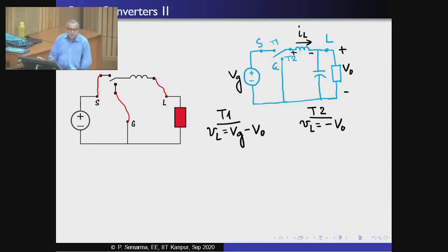Now, this is one interesting part. This is where we assign the signs of each one of these quantities. It is essential that you look at the circuit carefully before you put these plus or minus signs, because this is one place where students make a lot of mistakes. They get a little confused. So, don't do it. It's pretty straightforward. Just follow this sign around. If the plus sign comes onto the reference plus sign, then the corresponding voltage is positive. If the minus sign comes onto the reference plus sign, then the corresponding voltage is negative. Okay. So, do it straight up and do not get confused ever.